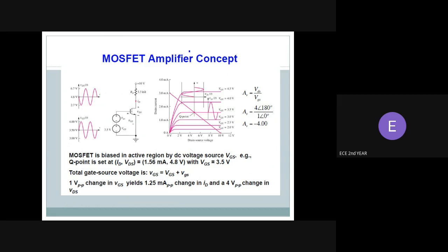MOSFETs can either be manufactured as MOS integrated circuit chips or as discrete MOSFET devices, such as power MOSFETs, and can take the form of single-gate or multi-gate transistors. Since a MOSFET can be made with either P-type or N-type semiconductor, we have PMOS or NMOS logic respectively. Complementary pairs of MOSFETs can be used for making switching circuits with low power consumption, called CMOS logic. A metal oxide semiconductor typically refers to a metal oxide insulated semiconductor.